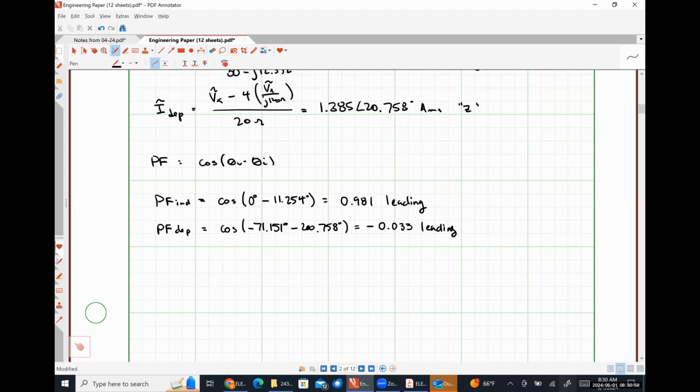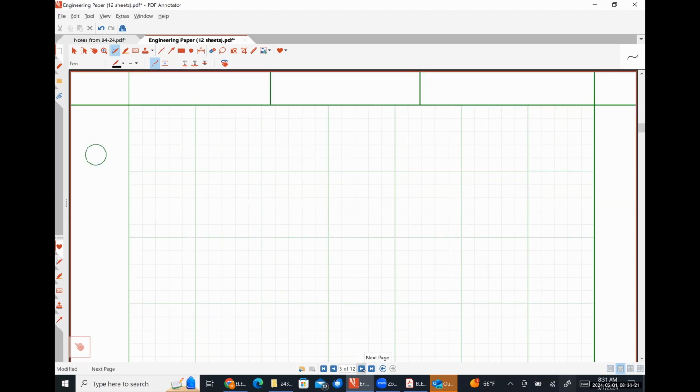And seeing that angle come out to be 88.091 kind of explains why this power factor is so incredibly small, because we know that at 90 degrees, plus or minus, it should be exactly 0. All right, so we did some things there. Let's find something else to do.